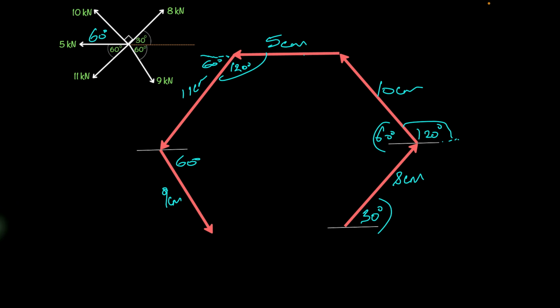So right here, I'm just highlighting right there with that green. That's 30 degrees right there. And if you notice, I've got the 30 degrees on the very, very same side right there as it is showing on the diagram. And of course, the arrow that we draw there for that 8 kilonewtons will be parallel with the 8 kilonewtons on the diagram as well. So the angle is a crucial thing that you need to have in the same position.